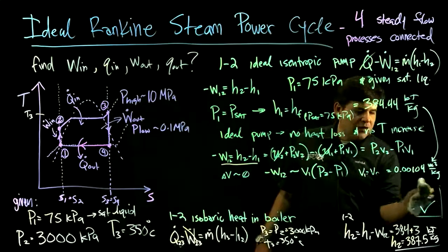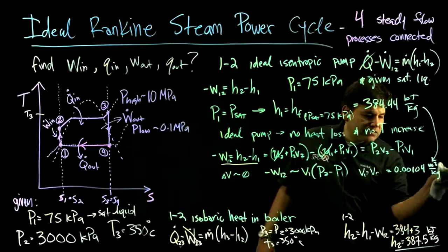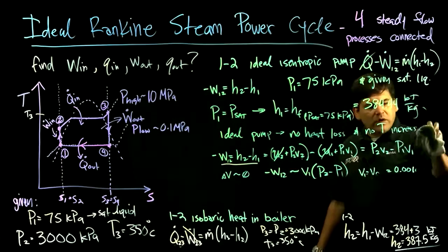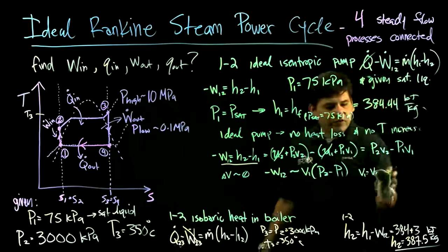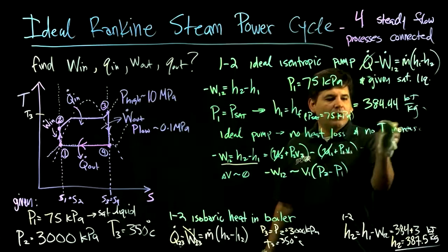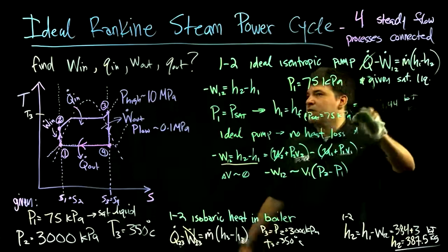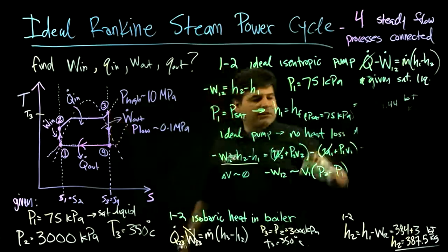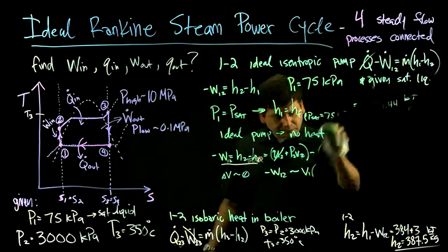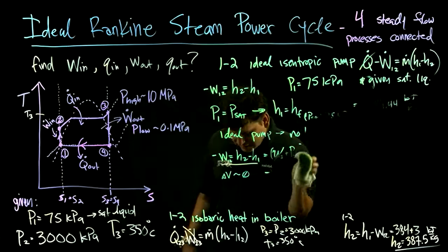So now that we know P3 and we know T3, we can go on the steam tables and see where we are, whether we are saturated liquid first, and that test will tell us whether we are there, or superheated, or compressed. And spoiler alert, a typical ideal Rankine cycle is designed to boil all the way to superheated steam. So we'll confirm that. I think I have this confirmation.